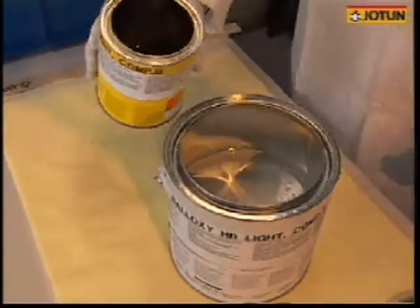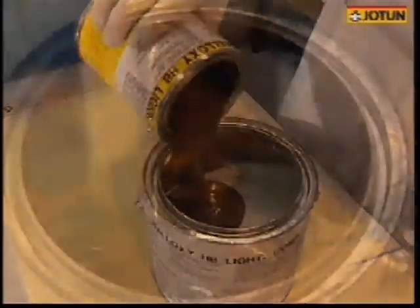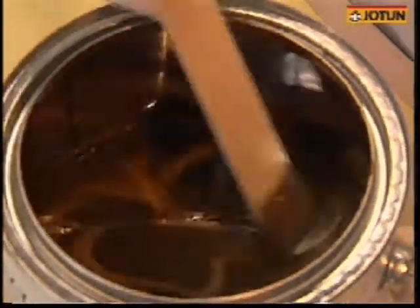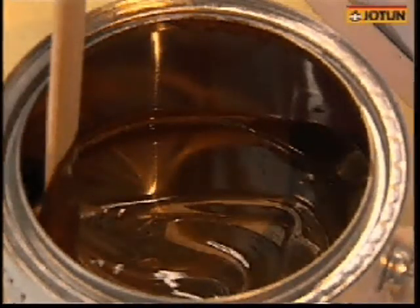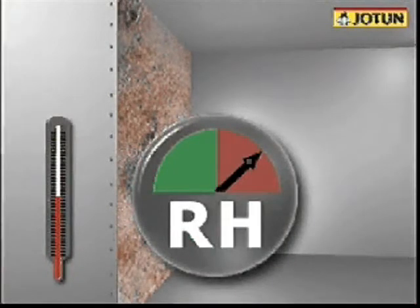Proper mixing of 2-pack paints is not easy to achieve. This is easily demonstrated by using this dark-coloured base, and even in a small tin like this, it's not sufficient to just use a stick for stirring. If you do, when you apply paint to a substrate, there'll be too many molecules of the base material in one place and an excess of the curing agent molecules in another area. Therefore, it's impossible for the complete chemical reaction to take place and establish a 3-dimensional network, which means the paint will not cure as it's supposed to.